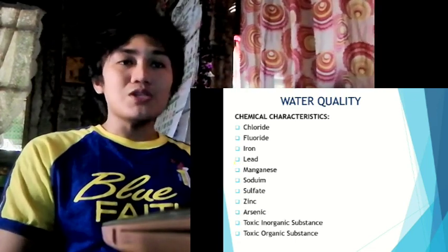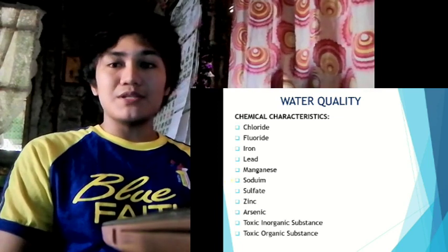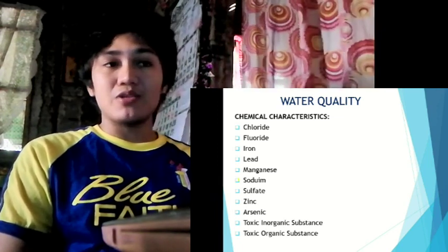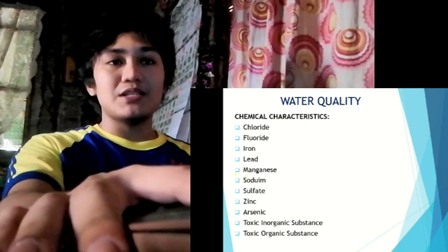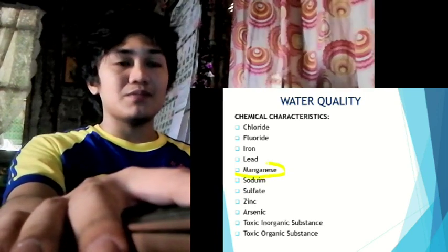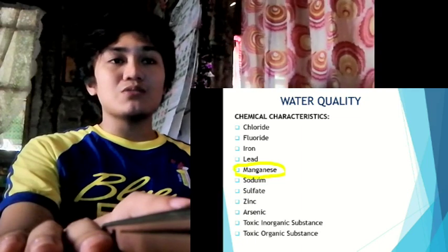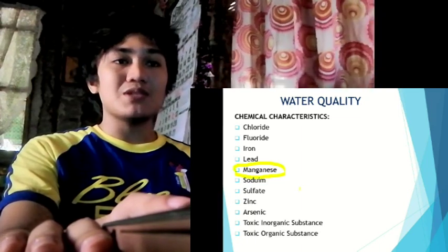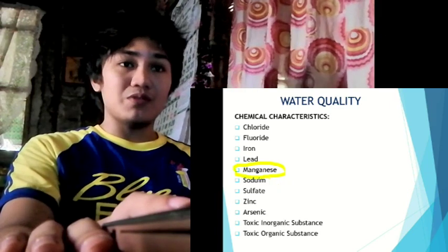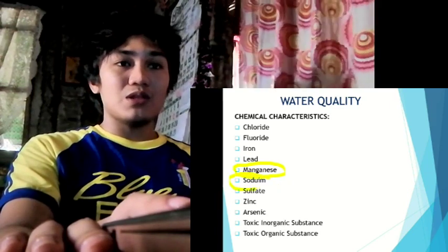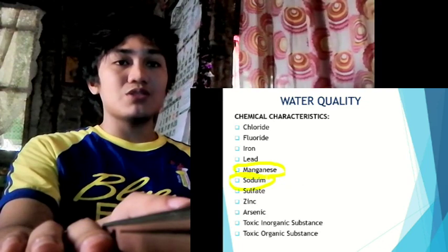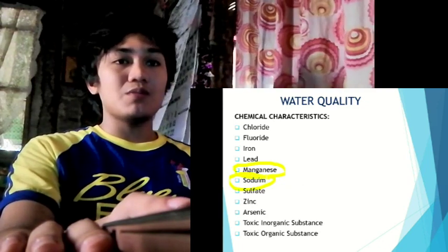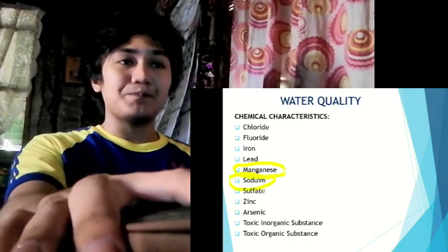Sodium. The presence of sodium in water can affect persons suffering from heart, kidney, or circulatory diseases or ailments. Sulfate. Waters containing high concentration of sulfate caused by leaching of natural deposits of magnesium sulfate, or what they call Epsom salts, or sodium sulfate, or Glauber's salt, may be undesirable because of their laxative effect.